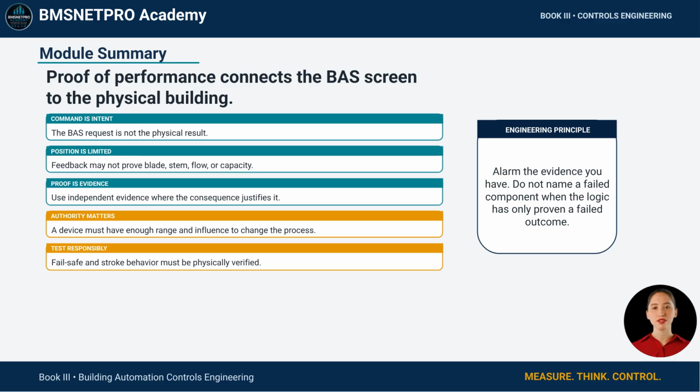Fail-safe behavior and stroke tests must be documented and physically verified. When a system fails, alarm the evidence you have. Do not name the component unless the sequence has actually proven the component failure.